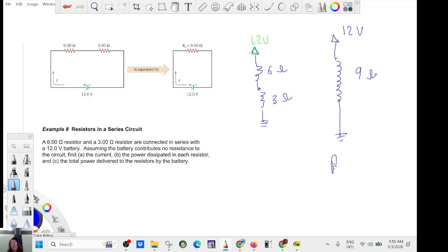So this is called the equivalent resistance. When you have a circuit in series, one resistance connected to another resistance connected to another, you just add the resistances, and this is called the equivalent resistance. Okay, it's easy to understand. This is just a mathematical trick to find, for example, the current drained from the battery.